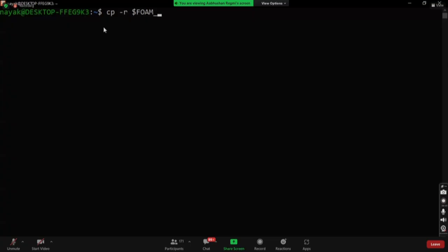The command is case sensitive, so please take care of the upper and lower case alphabets. So FOAM_TUTORIALS slash basic, then after that scalarTransportFoam with capital T, capital F, then pitzDaily.